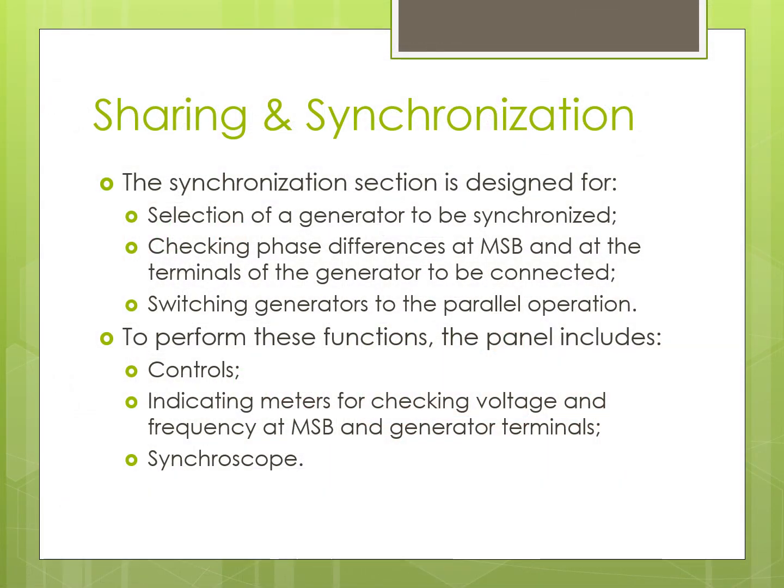Sharing and Synchronization. The synchronization section is designed for selection of a generator to be synchronized, checking phase differences at MSB and at the terminals of the generator to be connected, switching generators to the parallel operation. To perform these functions, the panel includes controls, indicating meters for checking voltage and frequency at MSB and generator terminals, synchroscope.